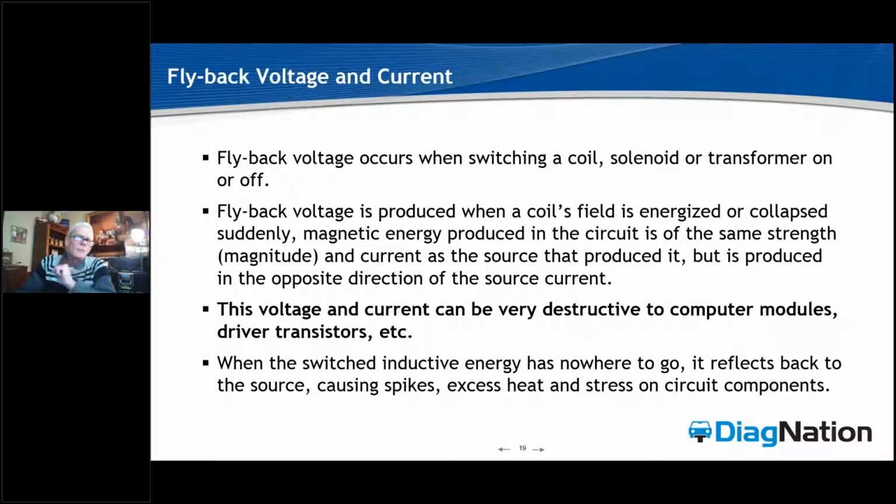Now, what's the beauty of that? If I test at the PCM connector and I test the exact same circuits with 2 other channels out at the fuel pump or the load device, guess what I'm doing, guys? If I do the math between the 2 channels, I'm now voltage dropping my wiring at the exact same time that I'm looking at the logic signal and the health thereof, and the output signal and the analog lines going to the load.